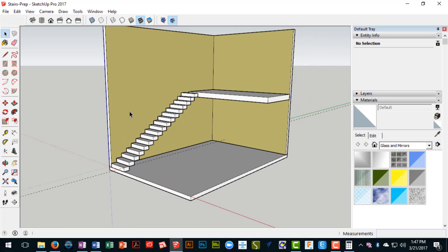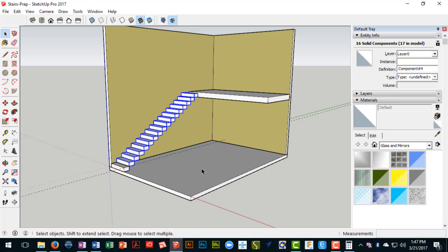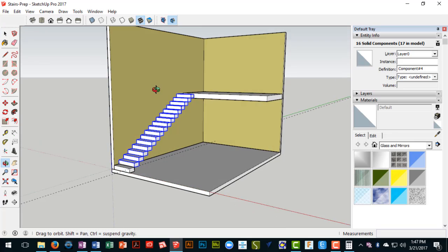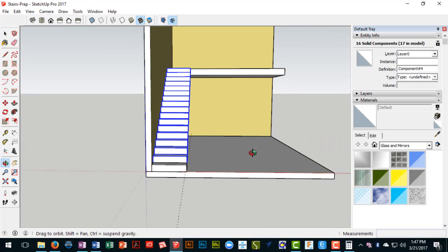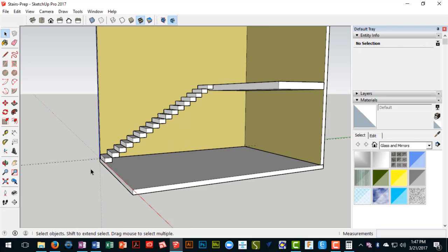So I'm going to use my Select tool, and I'm going to lasso from left to right. I'm going to make sure I get everything in there except for that first one. And you can see, because I didn't surround anything else in its entirety, except for these riser blocks, I don't have anything else selected. Let me show that to you again.